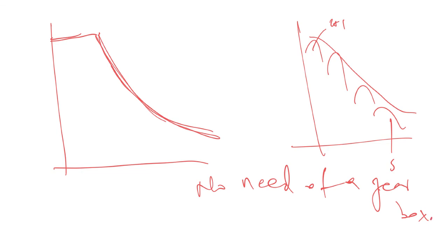Okay. Now, this is the speed. That's your torque. The other advantage is that at zero speed, you have torque. Your vehicle can receive torque at an instant of driving. You don't need to rev it to a particular speed, it has instant torque. Right. So that's one of the biggest advantages of electric motors for electric vehicle propulsion.